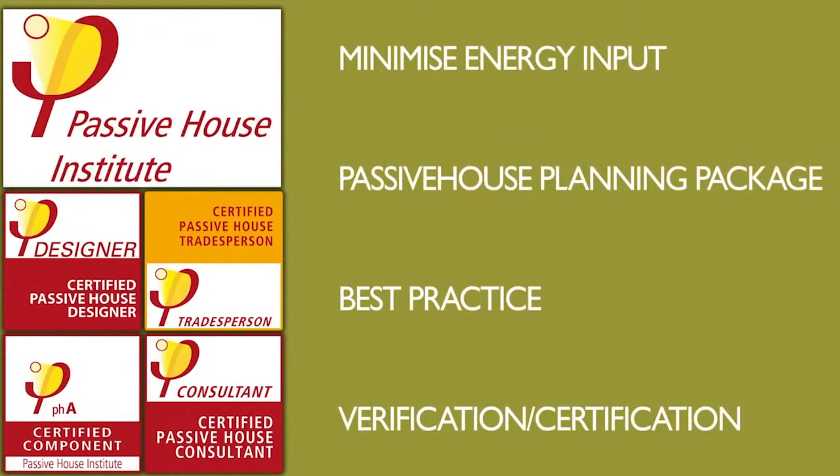The Passivehouse Institute provides software known as the Passivehouse Planning Package, or PHPP, to calculate these energy loads, and provides prescriptive guidance and details along with product certification. While this approach certainly simplifies the process and ensures rigorous adherence to good or best practice, it does not always allow designers the necessary flexibility to balance the full range of project requirements. In such cases, the Passivehouse guidance and principles can be viewed as best practice recommendations for designing buildings assessed by other means such as national building regulations.